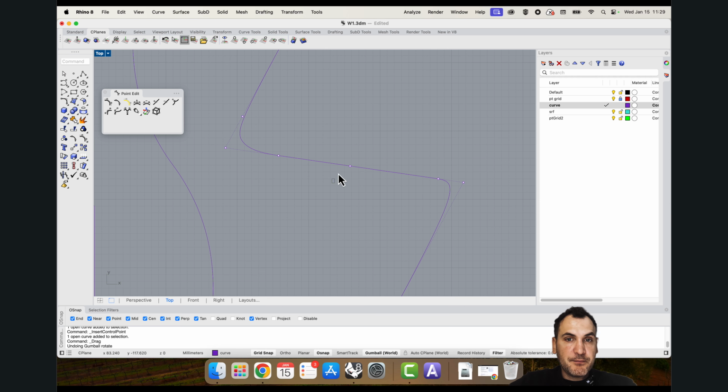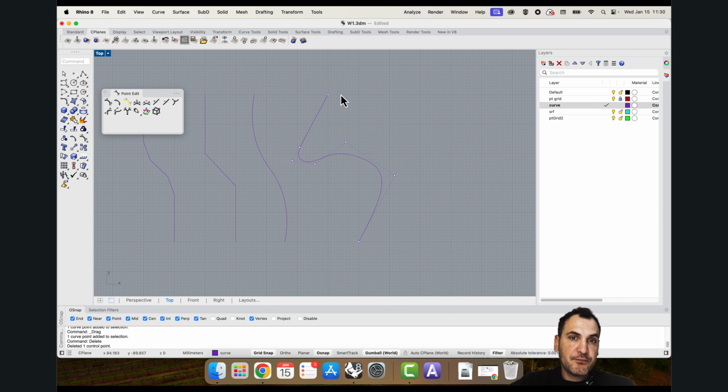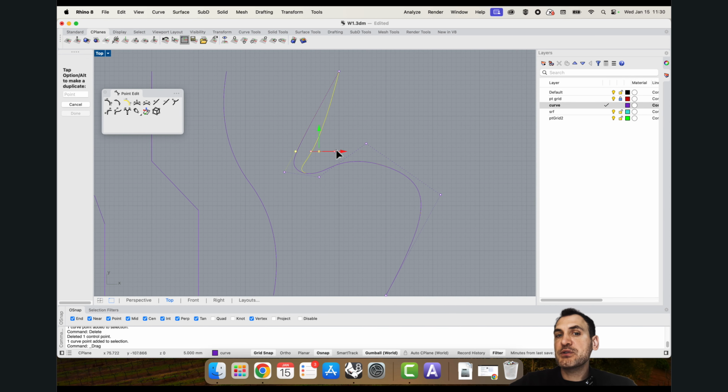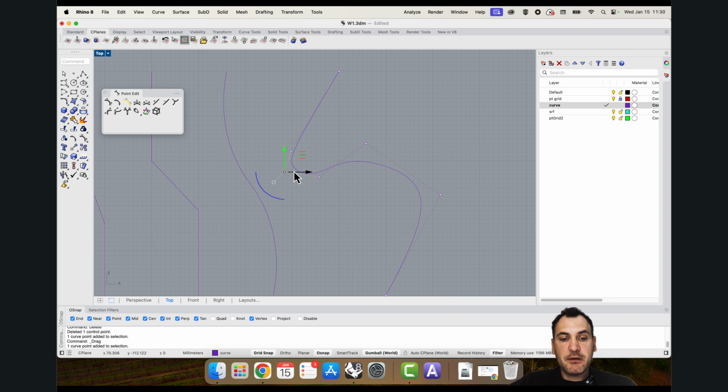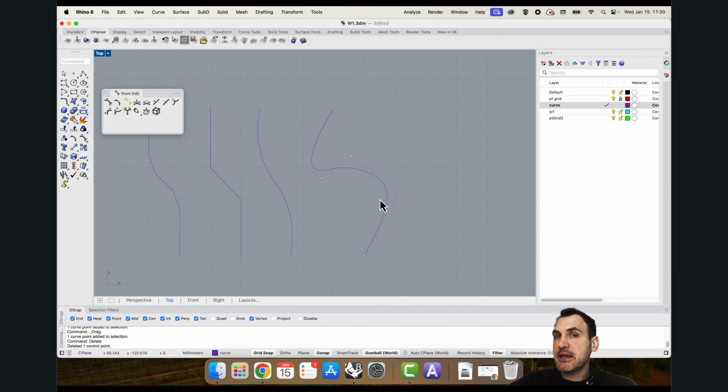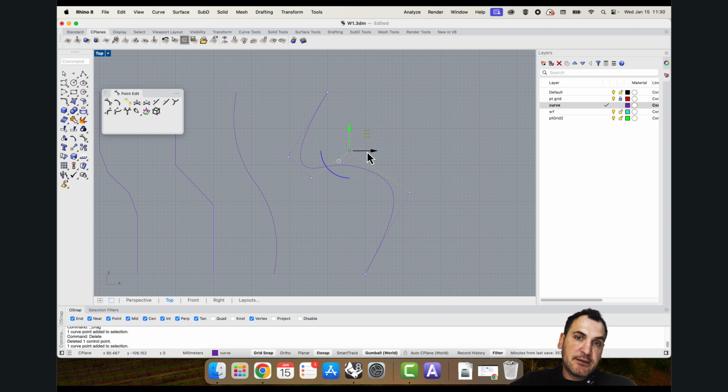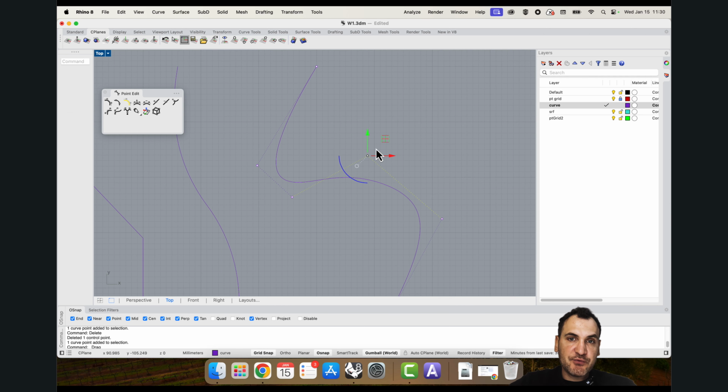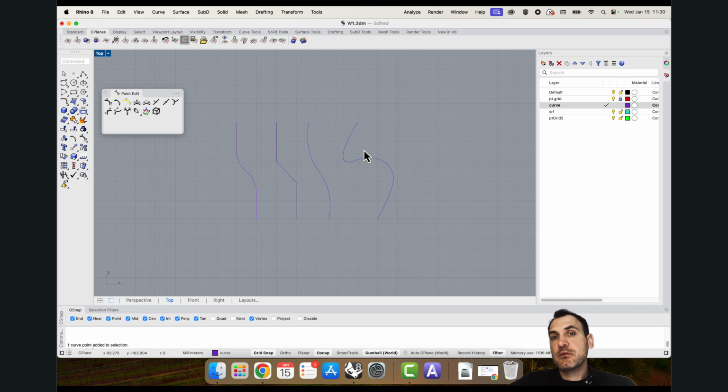So you can actually start increasing the information a bit more, or maybe delete some of the control vertices, and then control the topology a bit better, right? So if I want to have more curvature like this, like an S shape, I can add these points, and I can also move them around to control the geometry of the curve.